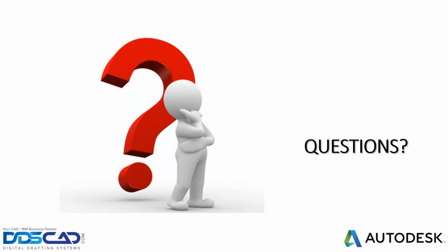I tested it out the first time I used it because I wanted to make sure: does it have to actually live there? No. As long as there's an instance of the Civil 3D object in there, it's in there. But of course, you will not be able to edit the object if it's from a data shortcut, if it's from a data reference. But it will at least show it to you in a drawing.